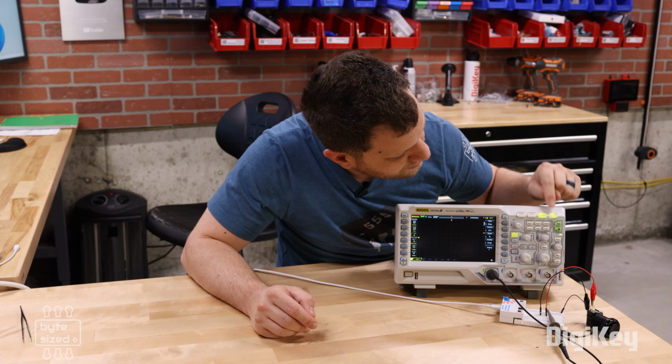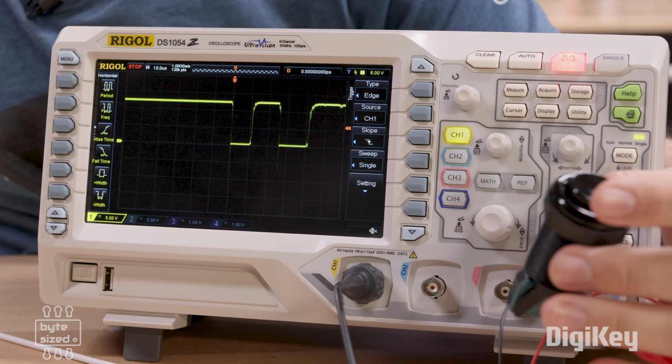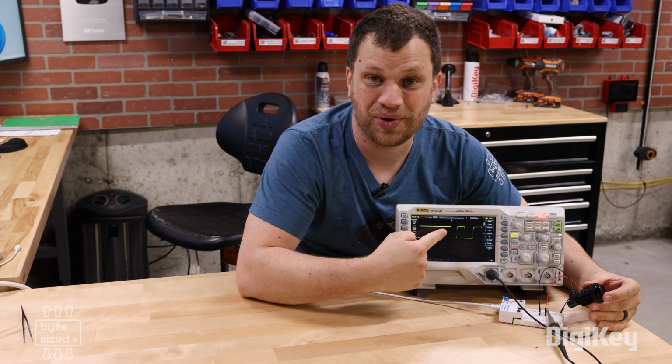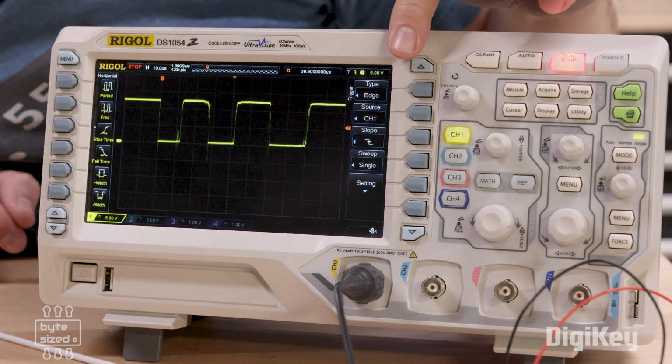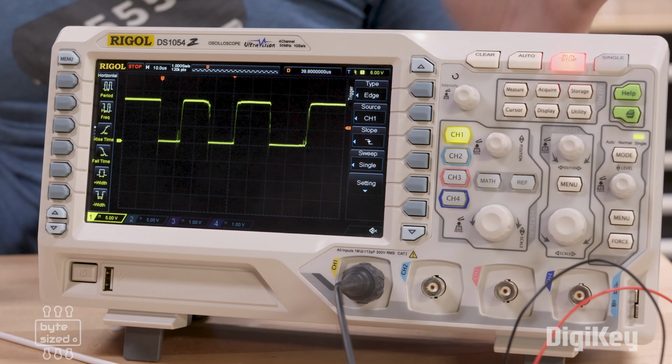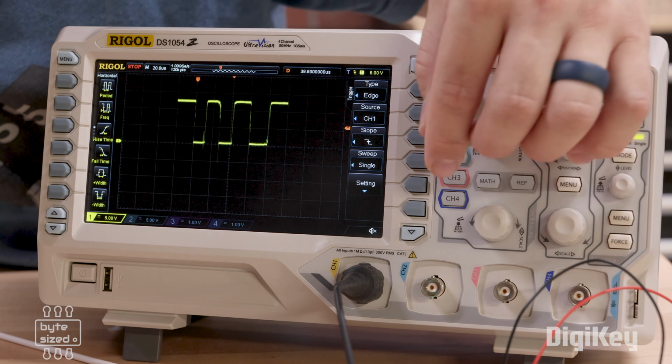The scope is still in single capture mode, and I'm gonna press the button, and there we go. We've got a falling edge. And as I described, we've got bouncing going on because this is a mechanical switch. It looks like it's still bouncing beyond the edge of my screen, so I need to adjust the horizontal resolution so that I can see everything.